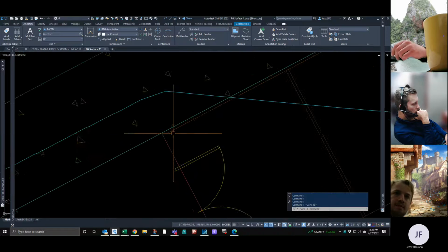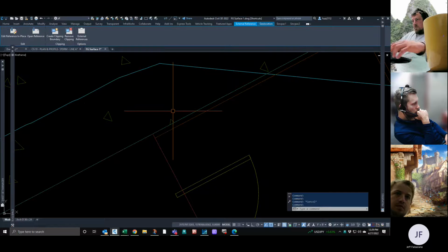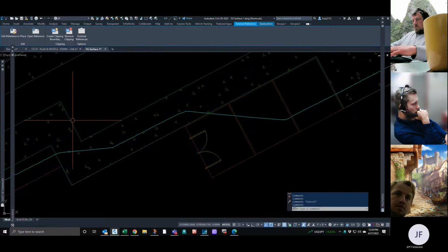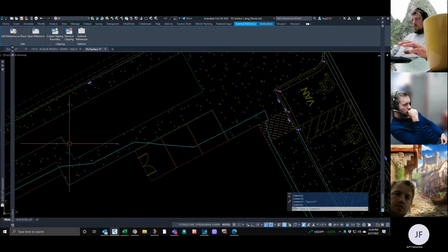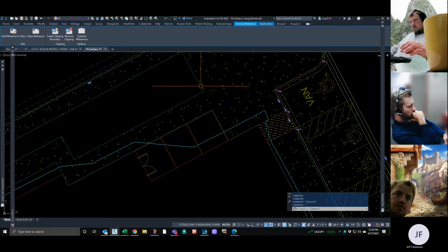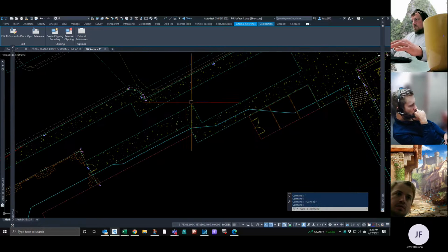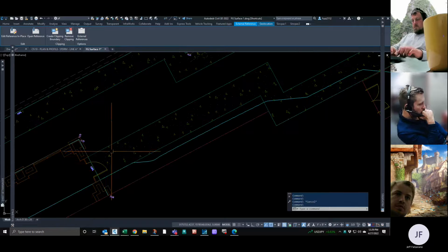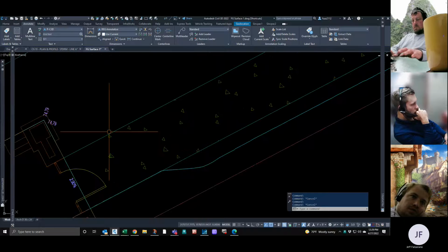This is going to be probably really close to finished floor elevation on that point, all the way around, and then you'll grade 2% in this direction, or I'm sorry, 1.8 in this direction to get the rest of your sidewalk in. Again, actually, we'll just start here.